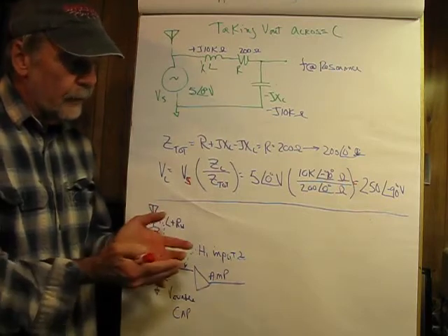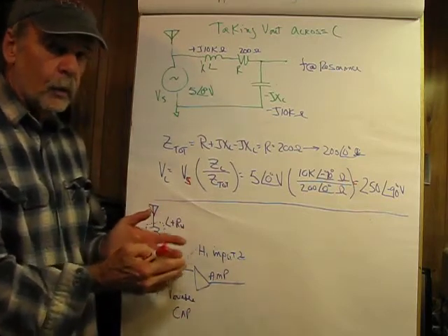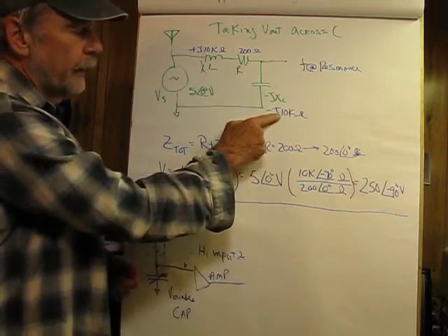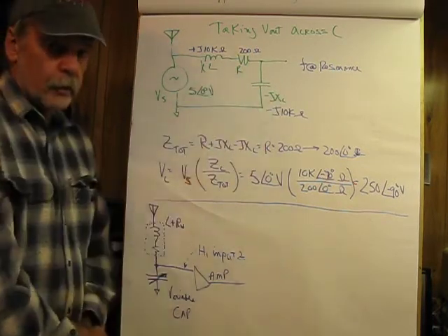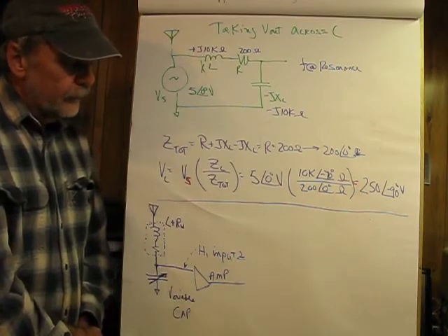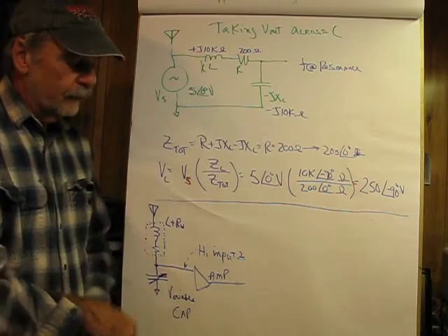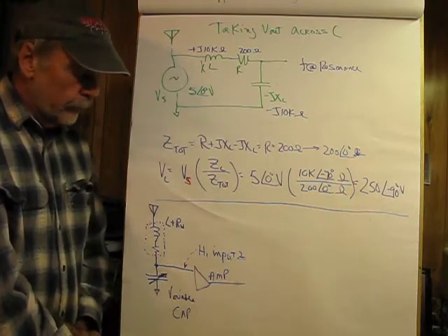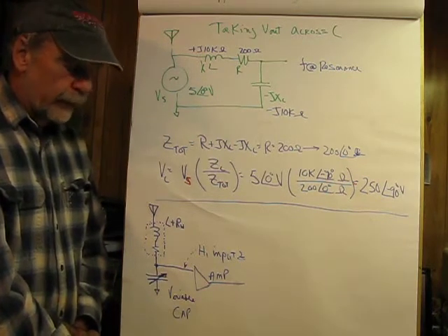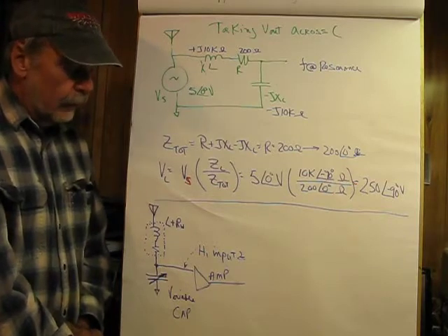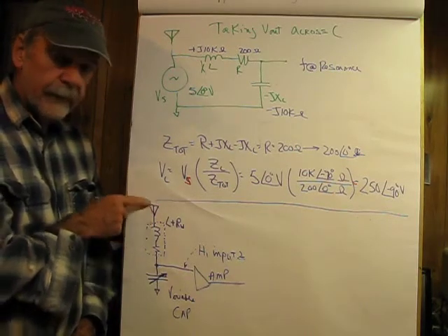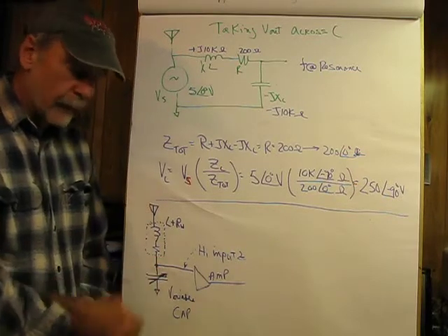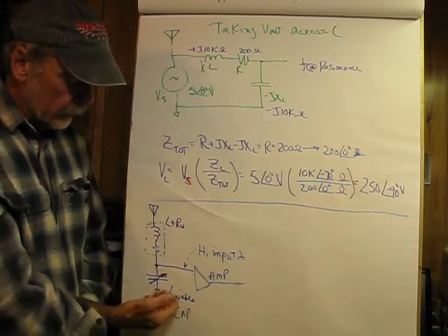So what we say here is we have a Q rise in voltage. Now what's the Q? It's 10K divided by 200 ohms. So we can get this amplifying effect, and it really happens. The only problem in a radio receiver is that the L relates to the antenna length. And with an outdoor antenna for AM, for example, it would actually look like this.